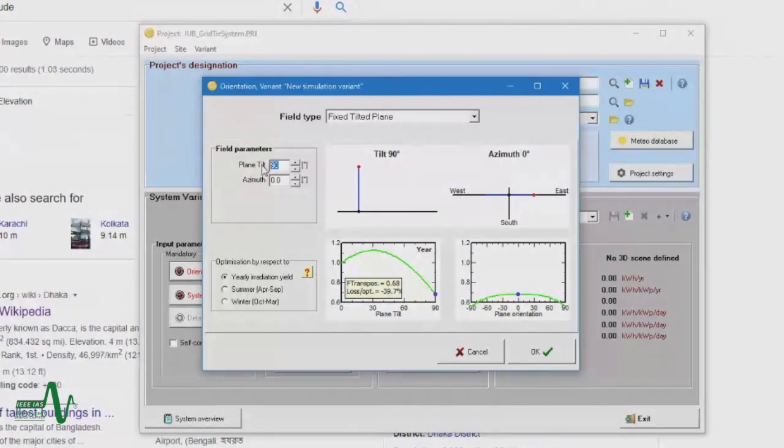I have heard from my students and some colleagues that in some other countries they choose the tilt angle as 0, so the solar panel will be flat, horizontal to the ground, and they said it's the best decision they have ever made. But the software shows a huge amount of loss. However, when you go for the economical analysis, you will find a lot of cost issues. Whenever you consider a tilt angle, there are a lot of infrastructure issues and costs. So they are minimizing the cost. However, we have to keep in mind that for energy harness, it will get a lower amount.